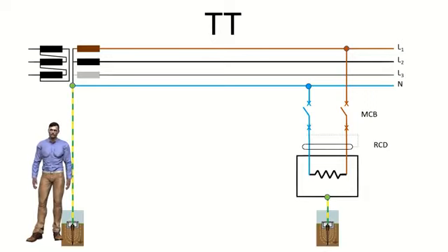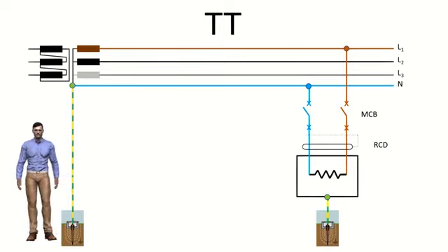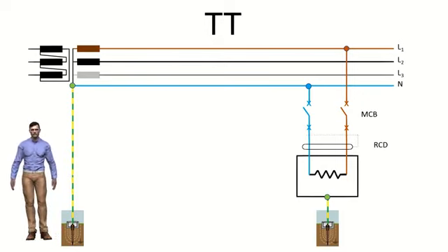If these two elements are separated, so that the differential is not damaged, the short-circuit current of the differential must be greater than that of the circuit breaker. In this sense, we must differentiate two different concepts, such as the maximum current that the protection supports, and on the other hand, the breaking current that a protection can withstand when opening its contacts.